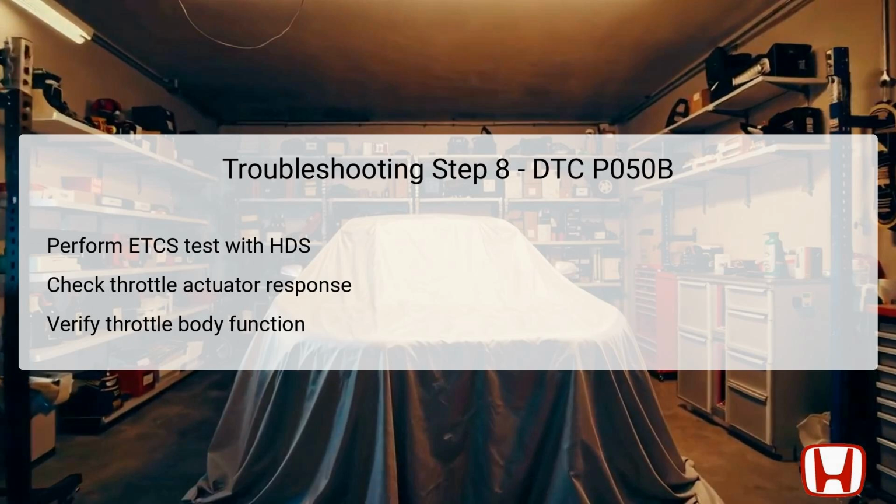If normal operation is confirmed, proceed to Step 9. However, if any issues arise during the test, it may indicate that the throttle body requires replacement. This step is vital for ensuring a consistent air supply during ignition, thereby preventing further issues in engine performance.